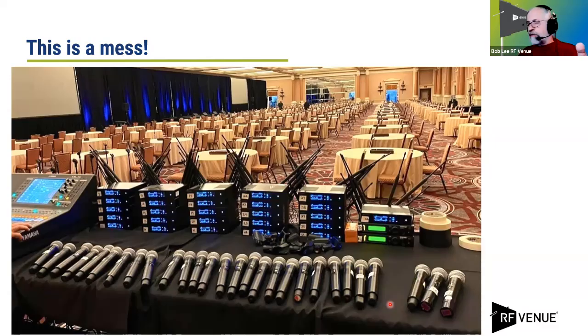So if you ever have to lay out transmitters next to each other like this, or even on a smaller scale, get some aluminum bread pans, like the disposable foil kind, and put one in each tray. And that will help shield the RF from getting into the next one. That's not related to distros, but it's a little user tip for you.